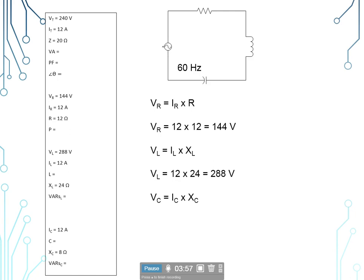Now we're going to go for the voltage drop at the capacitor. It is going to be equal to the current of the capacitor times the capacitive reactance. So we have that same 12 amp current, and we have a capacitive reactance of 8 ohms. Multiply that to give us a 96 volt drop across the capacitor.